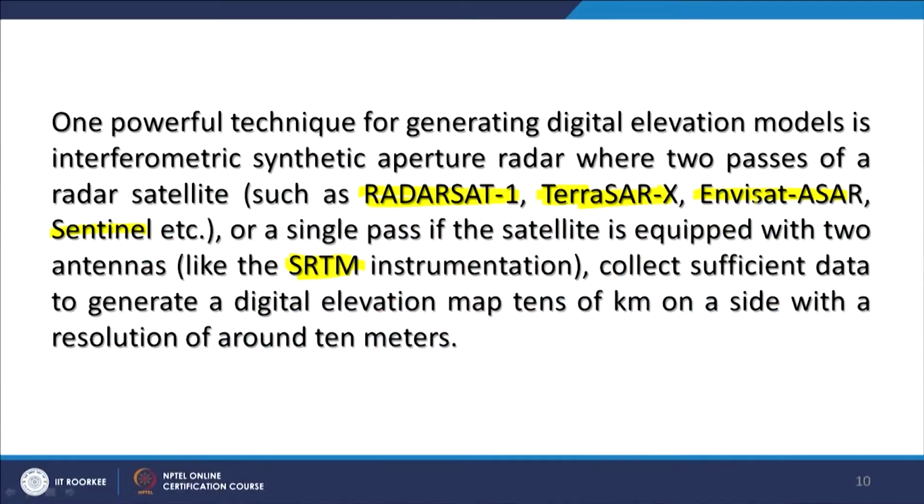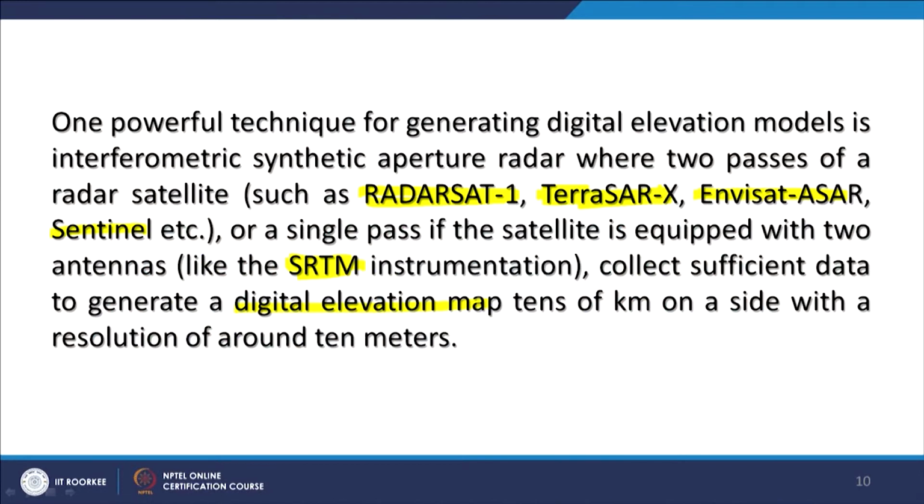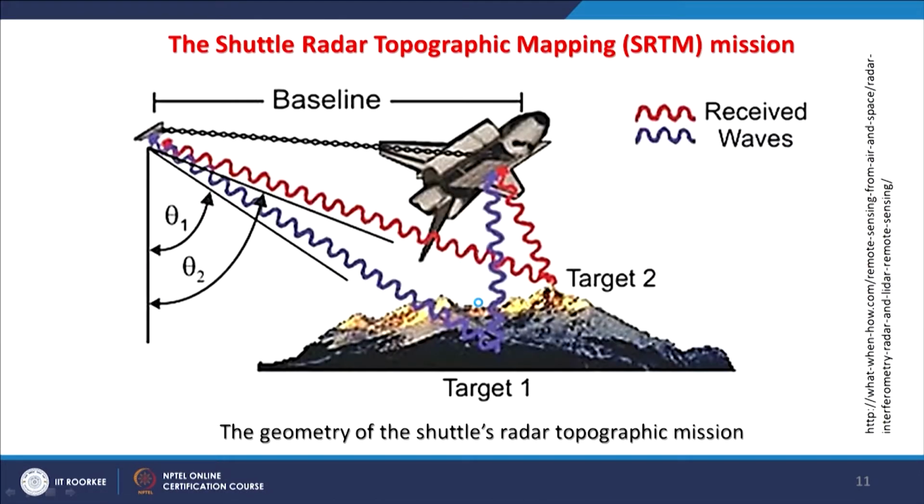So nowadays, there are a lot of choices. As I said earlier, now Sentinel data are available, and many of Envisat and Sentinel data are available free. So one can download the data, that is the radar pair, employ this SAR interferometry technique and develop a digital elevation model of relatively very high resolution. We have mentioned many times this SRTM, that is Shuttle Radar Topographic Mission. It was a mission, not a regular satellite, and the very innovative part was that